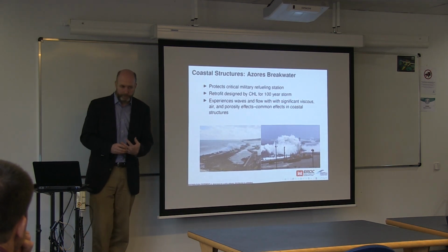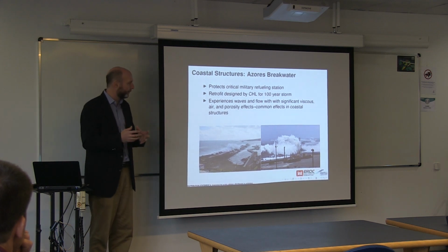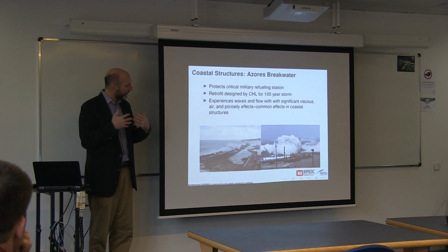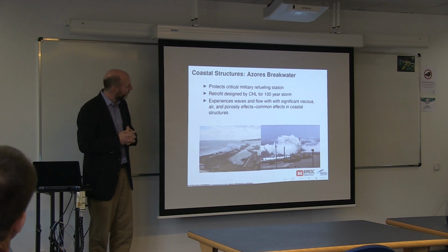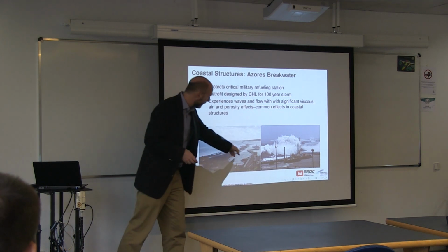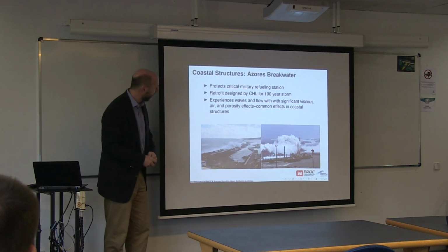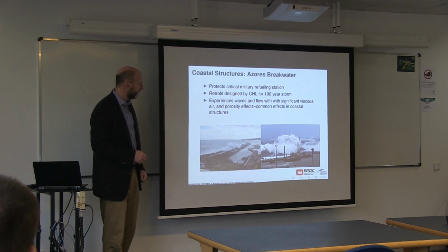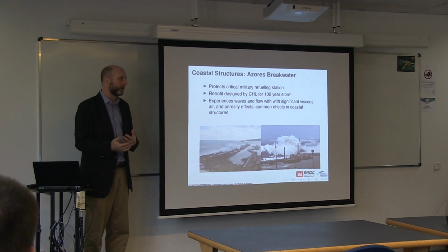Another area where we deal with things like sediment, although in some cases the grains can be quite large, but we're still essentially dealing with fluids and waves interacting with granular structures, is with breakwaters. This is a refueling platform in the Azores, and it has a large breakwater out in front of it to protect it from storm waves like that one. And these storms have enough energy to rearrange the armoring of the breakwater, these large concrete armoring blocks.